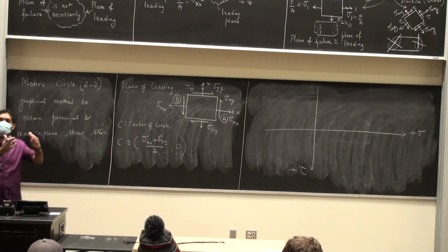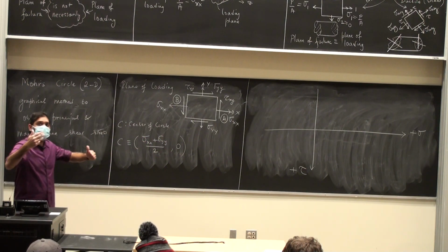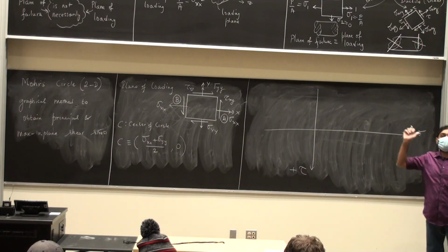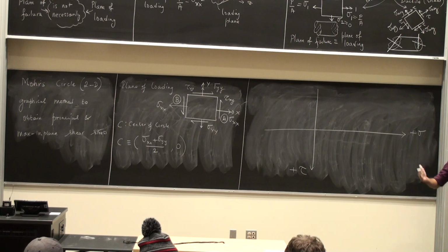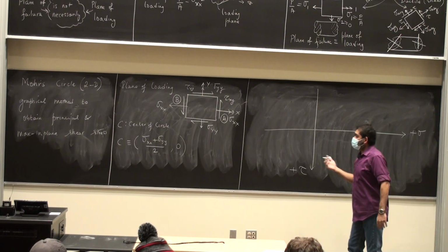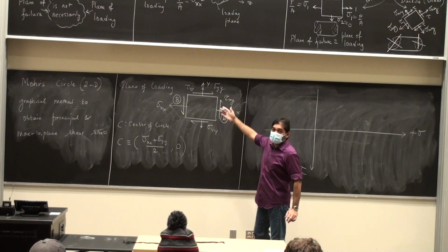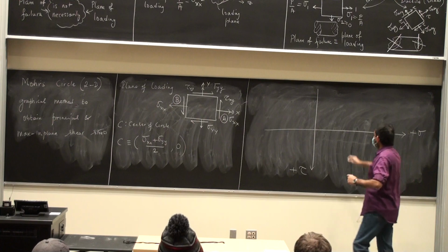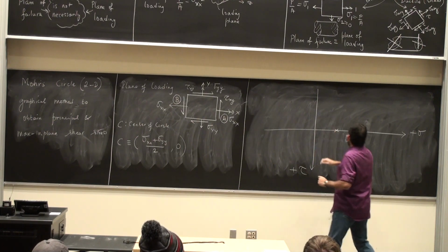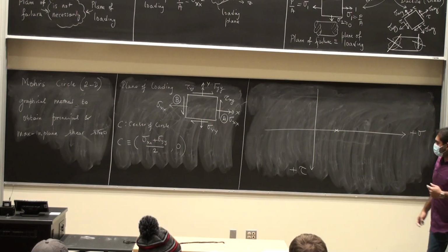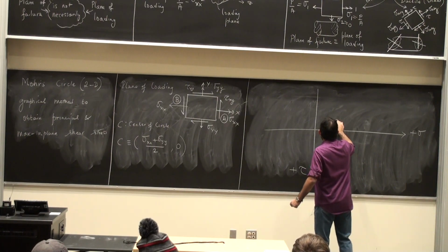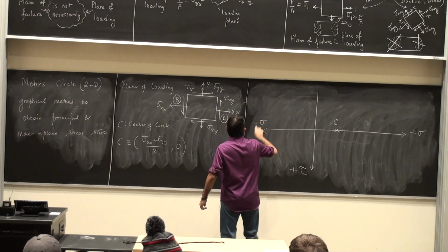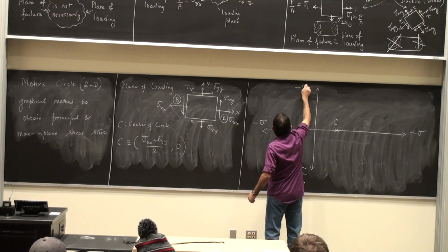All of you see that, right? There are 2 axes here. There's the sigma axis, there's the tau axis, which means if I'm specifying a coordinate on the plane, it should have 2 values. One on the sigma side, one on the tau side. The value on the tau side is 0, the value on the sigma side is based upon the state of loading, sigma xx plus sigma yy by 2. So you go ahead and mark this on the circle. So probably somewhere here. Okay, call that point as point C. This is negative sigma, and this is negative tau.